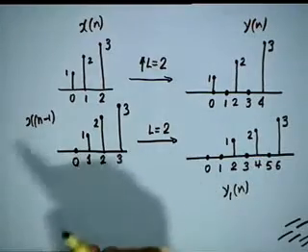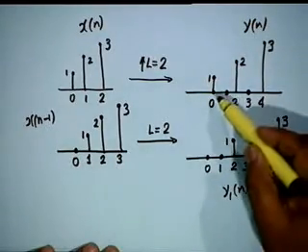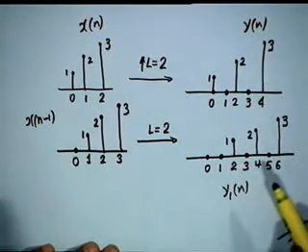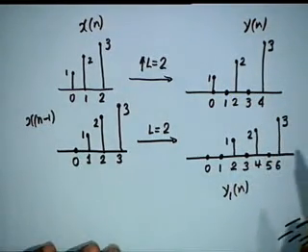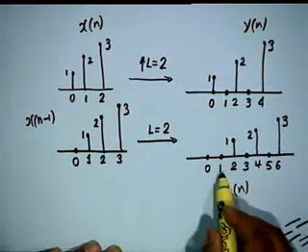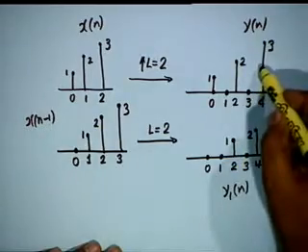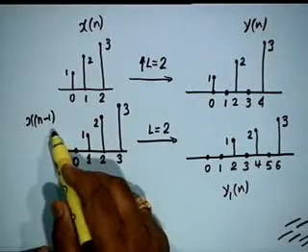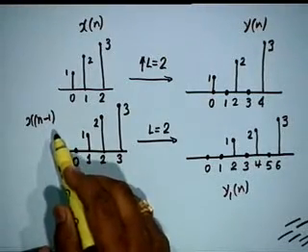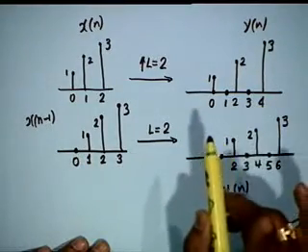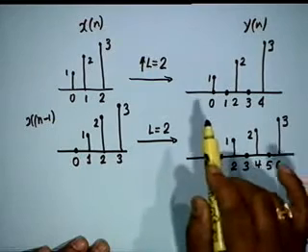Now, one of the comments was that the waveform, that is 1, 2, 3 with zeros in between, is preserved. Okay, waveform is preserved, but what about the delay? How many samples is this delayed by in comparison to this? 2 samples, whereas x of n minus 1 should have led to y of n minus 1. That is, if this was delayed by one sample, we would have agreed it is a time invariant system.